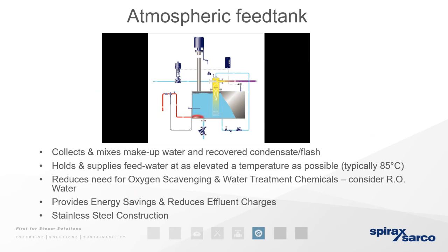Many times we have said that we would want this hot well to be as high a temperature as possible, and that is true. But again, you have to take into consideration what temperature the feed pump can handle. Otherwise, you will definitely cause cavitation through the pump. A high feed water temperature has three benefits.